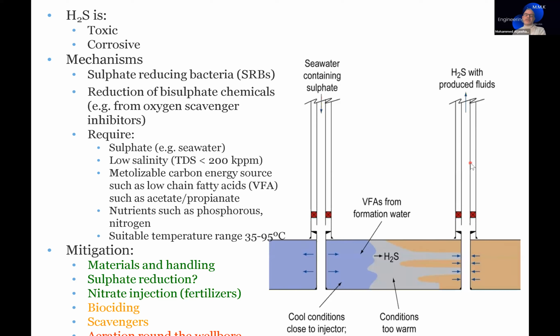This H2S can be very harmful inside the wellbore. I mean the chemical and mechanical issues we have seen because of this. So we need to consider the completion of the wellbore, because these formations may be producing H2S. So it is a remarkable consideration for the completion, and what type of casing and tubing need to be installed inside the wellbore.